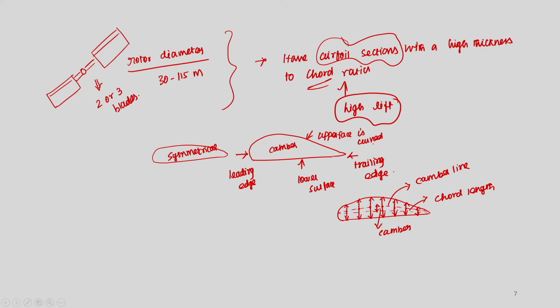right. So, that is why it is said that if you have a high thickness to chord ratio, then your lift force may be high, right. So, here the concept is that we have theories based on which you will get this lift force, which is the upward force. One is based on Bernoulli's principle. The second one is the flow turning principle.